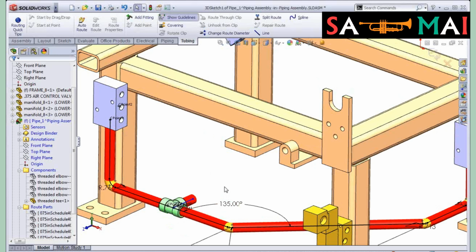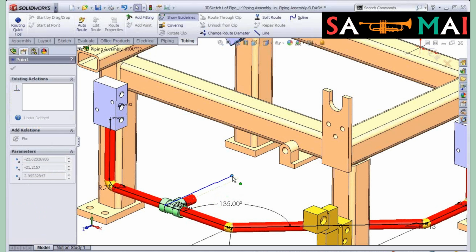If you want an exact specific direction, like you wanted to run off in 123.5 degrees, the thing you do is draw a reference sketch line first. Then when you drop your T in there, it snaps exactly to that angle. So that's one of the more advanced things that you would learn about in a routing class. Those are the 2 simple ways to orient your part.